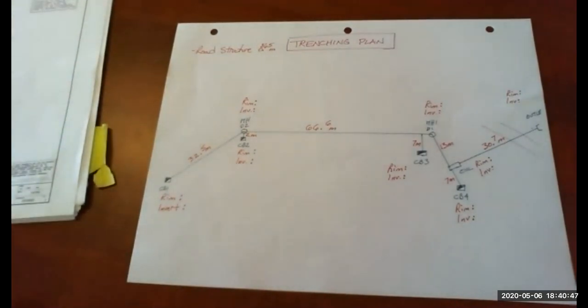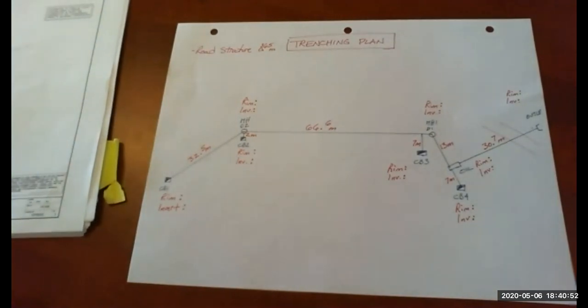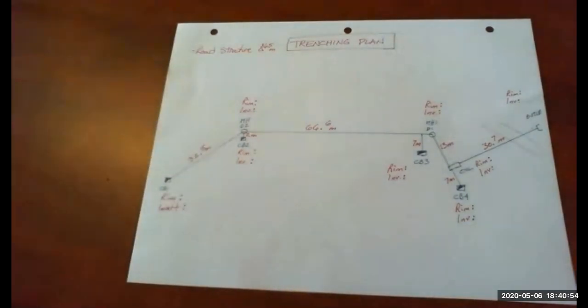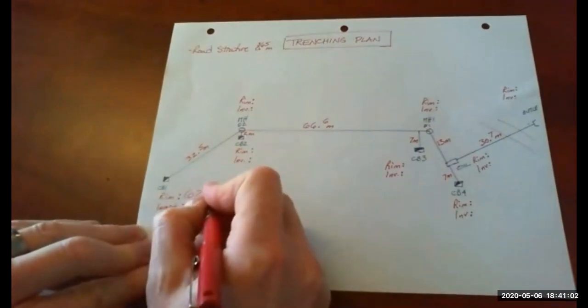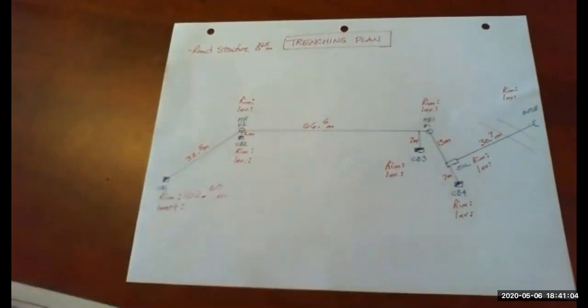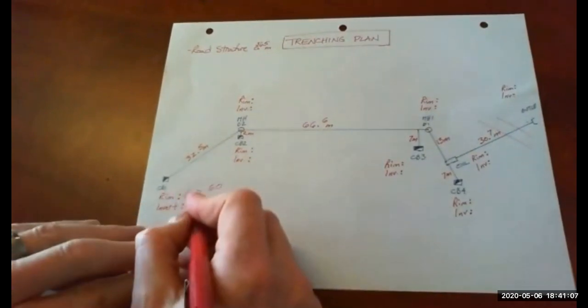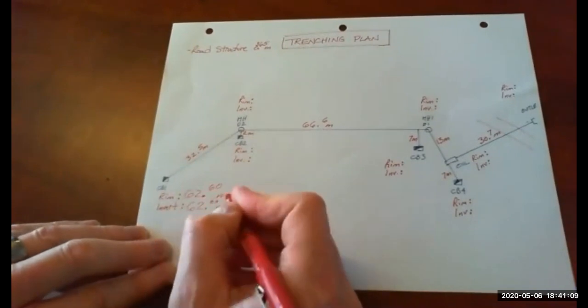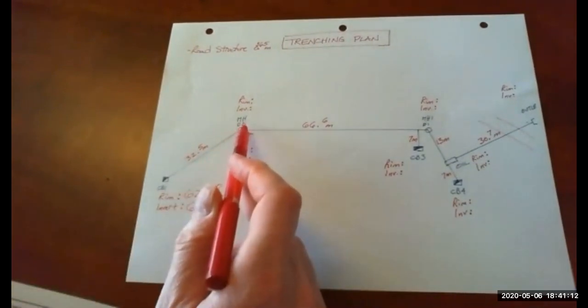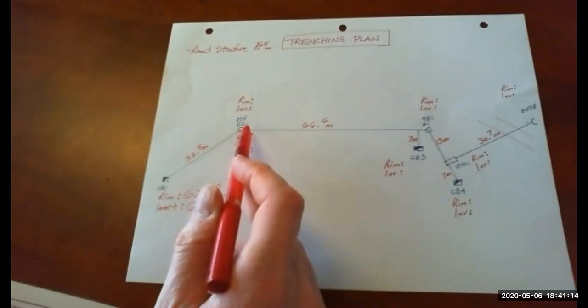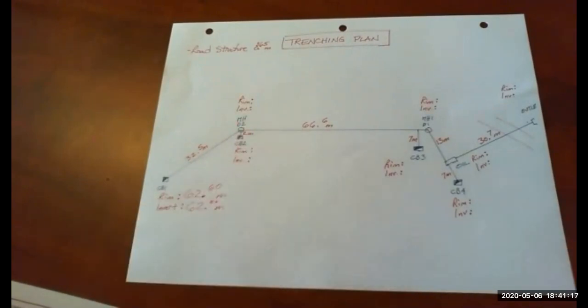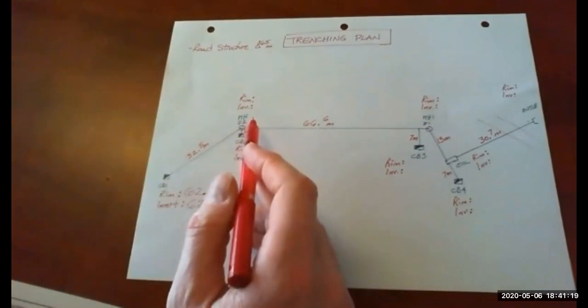So looking at my drawings, I see they're very tiny. So catch basin 1, we're told rim is 62.6. And the invert of the pipe is 62. So for manhole D2, next in line, we're given the invert. So we've got an invert in and an invert out.